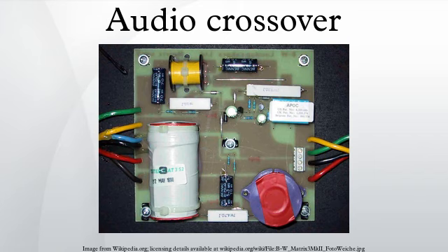Full-range drivers have a single acoustic center, and can have relatively modest phase change across the audio spectrum. For best performance at low frequencies, these drivers require careful enclosure design. Their small size requires considerable cone excursion to reproduce bass effectively, but the short voice coils required for reasonable high-frequency performance can only move over a limited range. Nevertheless, within these constraints, cost and complications are reduced, as no crossovers are required.